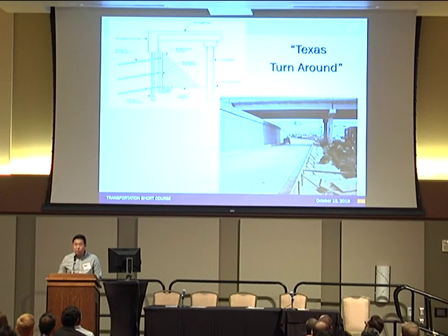A couple of challenges or constraints: the soil nail should be installed through the existing foundation element. There will also be a headroom constraint, especially for installing the soil nails. Typical installation angle is about 15 degrees, but you can use up to a 5-degree angle. You can also install the soil nail in segments.